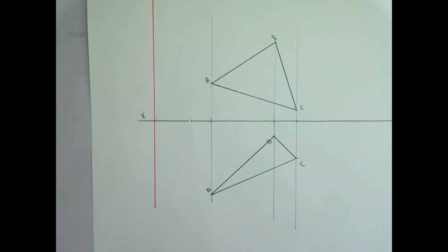The next part that we're going to look at here is how we might find an edge view of the plane. So to find an edge view of the plane, we're going to find a true length line on the surface of it, because if we find a true length of that line and get a point view of it, one of our key principles of DCG is that if you find a point view of a line on a surface, you find an edge view of that surface. So we're going to find a true length line, and then by finding that true length line, we'll get a point view of it.